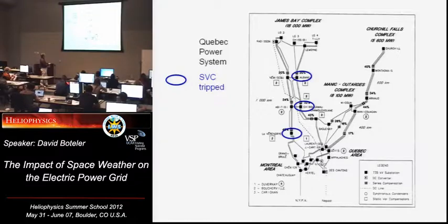As I was saying about the current flow, we think GIC is flowing across here. It's these substations that are being affected. And right, all four tripped out. Then without that to maintain the stability of the network, the voltage started to drop, and you started to get surges of power up and down the network. The load end was going out of phase with the generation end, so the power was swinging up and down like this.